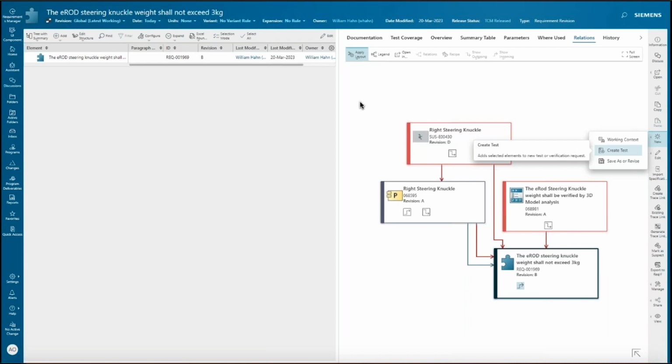And solve that system that you put together very quickly, because we're using 2D components, we're not meshing anything, right? And for very large systems and very high level analysis, it can be very accurate in providing results, whether it's hydraulics, electrical, mechanical, just using those physics-based equations and solving that system. A lot of customers I talk to are using that up front a lot, especially in the concept phase when I don't have a CAD model, right?